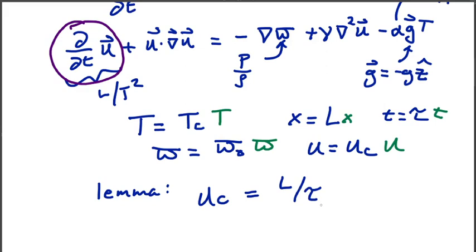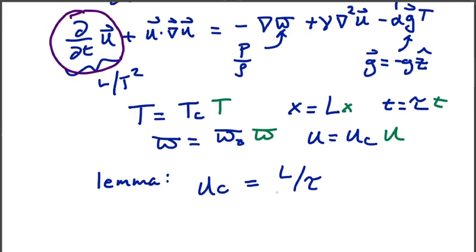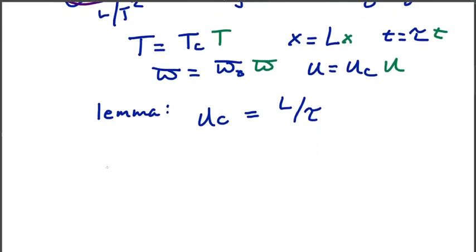All right, so let's start non-dimensionalizing our equations. Let's start from the top, from our divergence of u equals 0 equation. So this is our dimensional part. We're going to pull out our characteristic u and our length scale here, and then we're going to have our non-dimensional divergence dot u equal to 0.